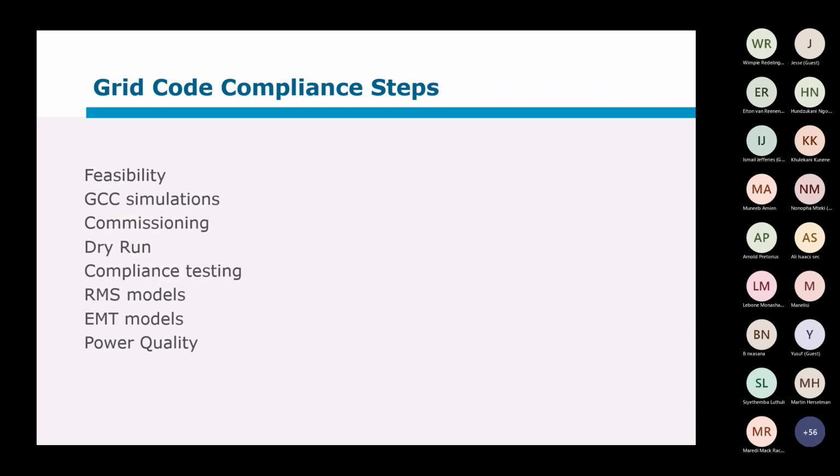How did you see that question, which Mark posted from Ishmael? I saw it on WhatsApp. Oh no, I haven't looked at WhatsApp. No, it's the same. It's just asking the grid code requires control functions, even for category A3. So that's obviously 100 kilowatt up to 1 megawatt installations, unless exemption or revision is required. I don't know if you want to comment on that. Okay. Yes, the grid code does require that, which implies there's SCADA to the generator's terminals, to which he must be able to respond. I think it's basically only start, stop, and something else.